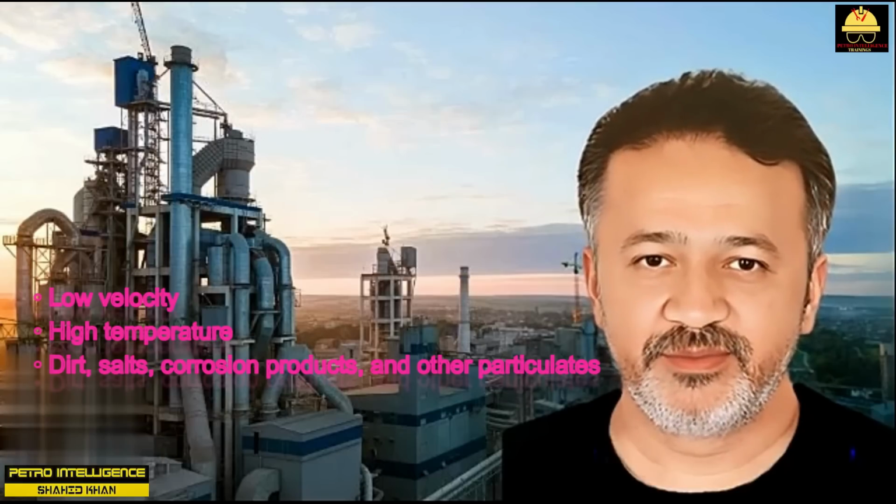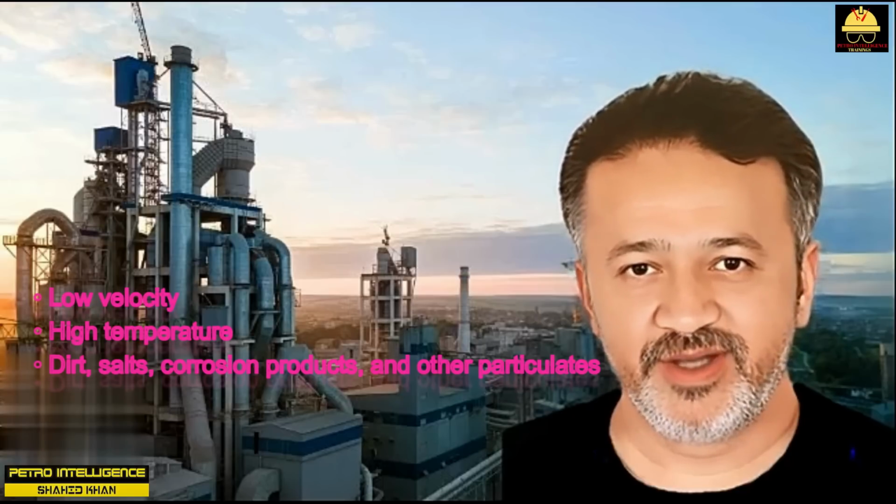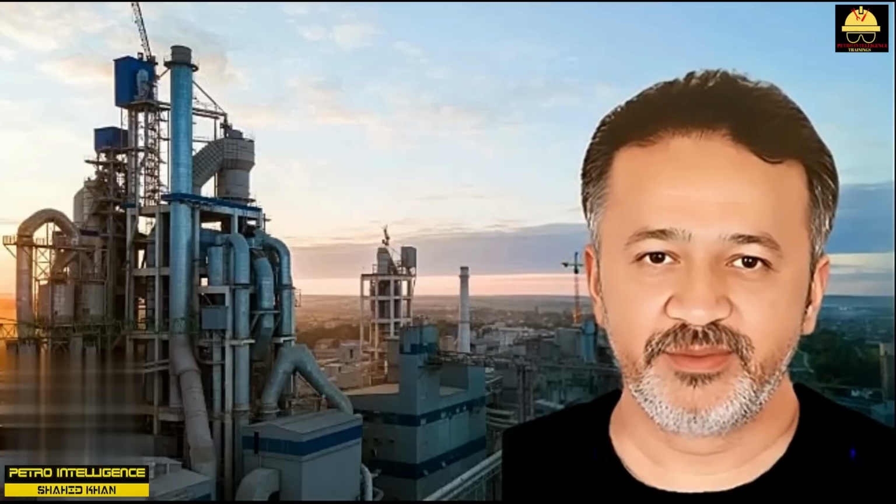Crude oil, like many processed fluids, will eventually foul and plug heat exchanger tubes. The tendency to lay down fouling deposits is accelerated by low velocity, high temperature, dirt, salts, corrosion products, and other particulates. The crude oil is being heated by a hot oil stream circulating through the exchanger's shell. Even though the exchanger is new, the flow of crude through all the tubes is not equal. Some of the tubes naturally run somewhat slower, and in some of the tubes, the crude oil will run faster. Those tubes that start running slower tend to get hotter.